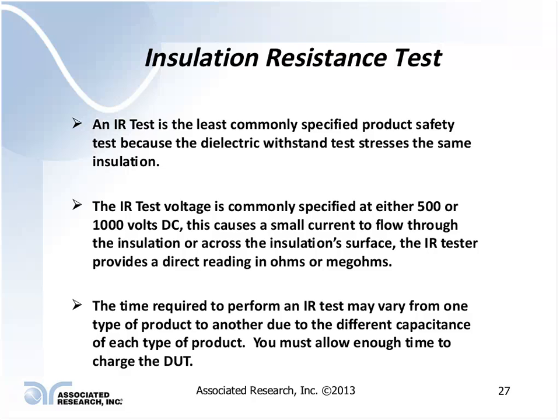The time required to perform an insulation resistance test is going to vary depending upon the product that you're testing. Products that have a much larger capacitance require a longer duration IR test, and you must allow for enough time to charge up the device under test before you take an insulation resistance reading. If you take a reading while that capacitance is still charging, it's going to be an erroneous reading because you're measuring essentially charging current rather than the actual leakage current due to the actual insulation resistance of the product itself.